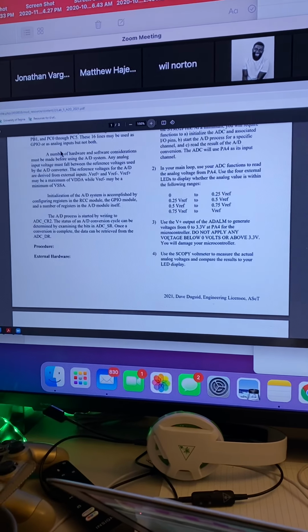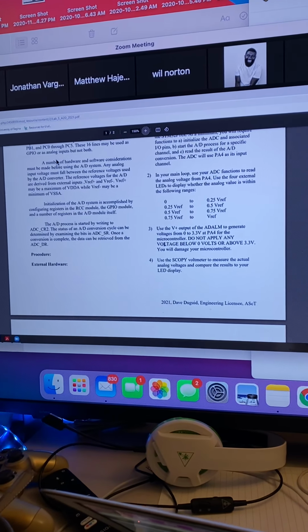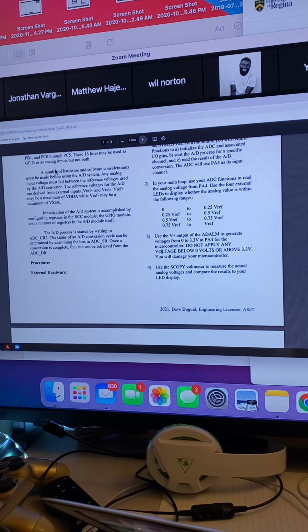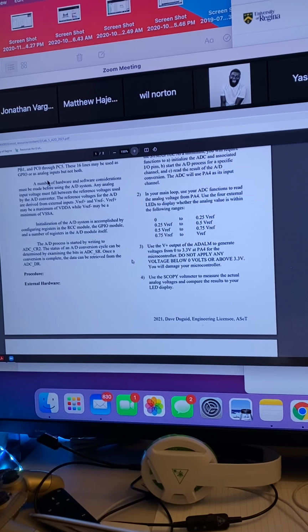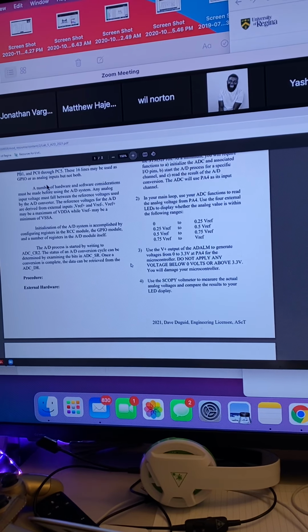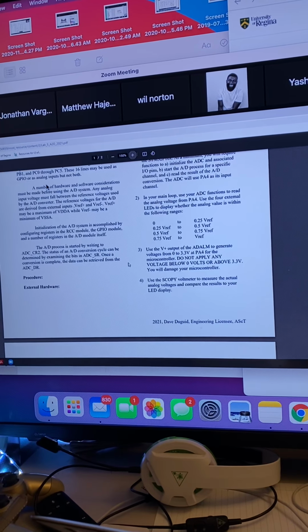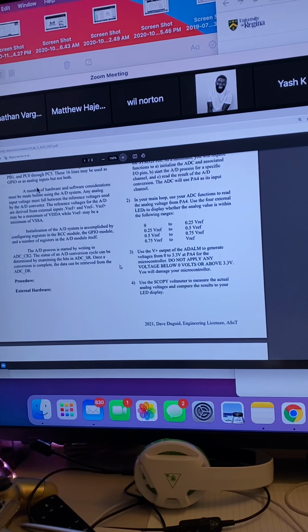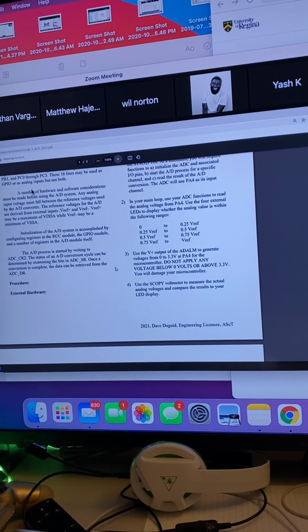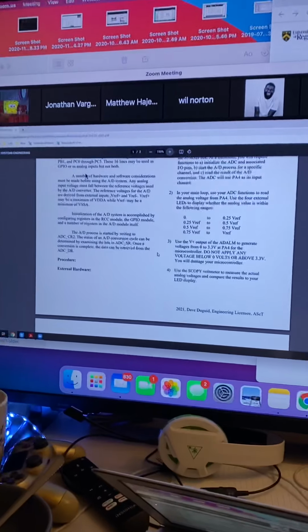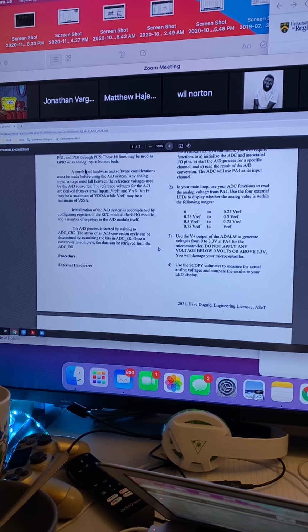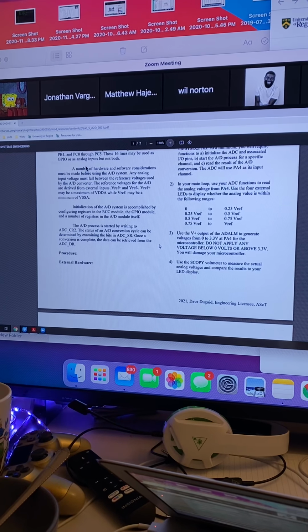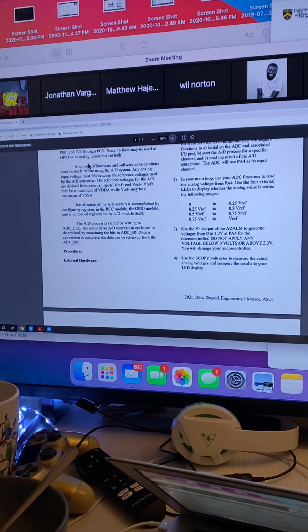Now, really, this should be happening on a continuous basis. It should be happening on some regular basis. Maybe you want to do something like use SysTick to make this happen every half a second so that your LEDs will update every half a second. Or maybe you want to do this every whatever time frame you want. But now, as you change the input, at some point in time, the output will update. So you don't have to do it at processor speed. You can slow it down, use SysTick to generate a scheduler for you.